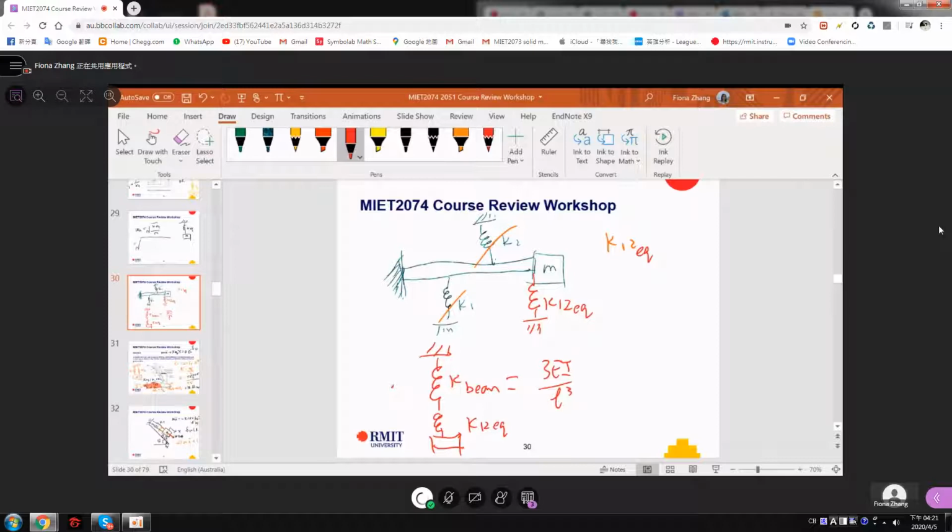If you have a computer, you can search for a beam deflection table, and you will find an expression for cantilever beam deflection. F is mg in this case, if you have a mass here. I remember someone asked what F is; probably I answered already. The expression is F over 6EI times (3L minus x), which you can find from the beam deflection table.